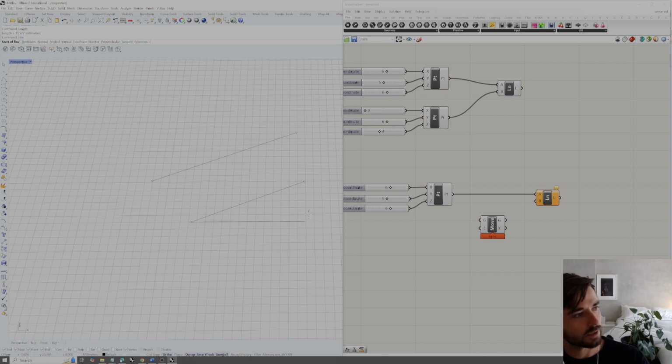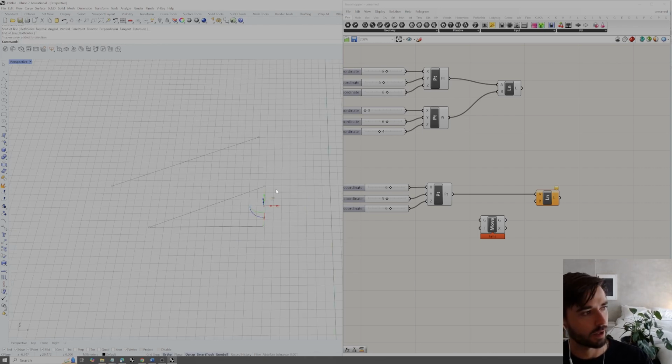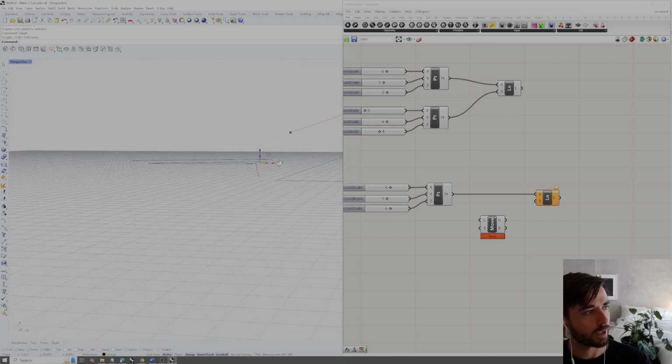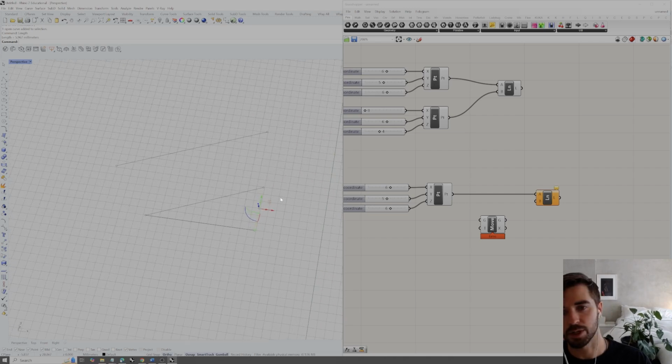We can then draw a second line from this endpoint up, and this will give us the y component value of the vector. So if I type in length, that's the y component value of the vector. And we can see that that's flat, so there's going to be no z component of that vector. So we have 2 values that need to be plugged in with a third value of 0. That would give us the vector for this move translation.